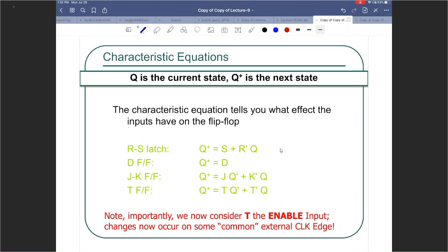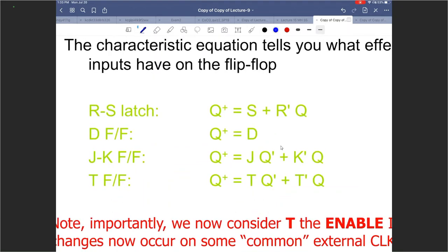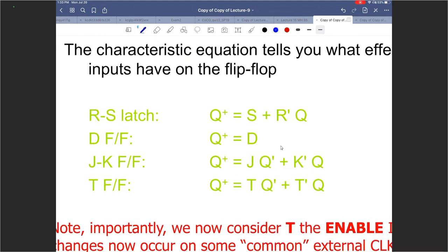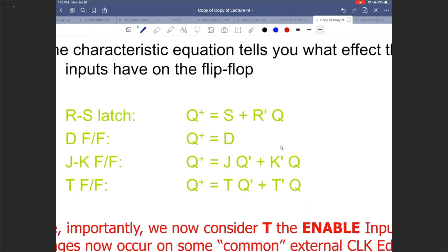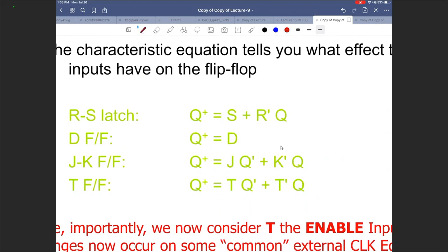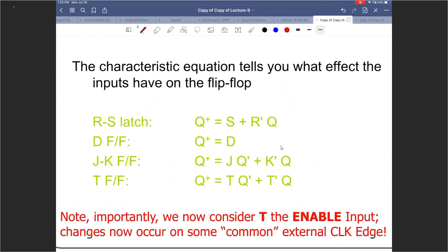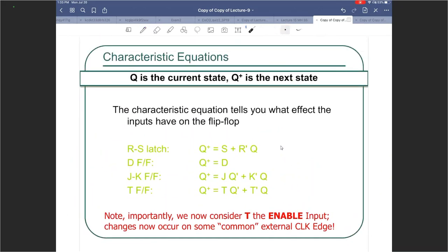Okay. So when we are talking about the flip-flops, the one thing that I would like to summarize is all the characteristic equations, the next state tables, and the excitation tables all in one place. So if you can think of any sequential element, one is the SR latch. The characteristic equation of this is the Q plus, which is the next state, right? Q plus is the next state, and Q is the current state.